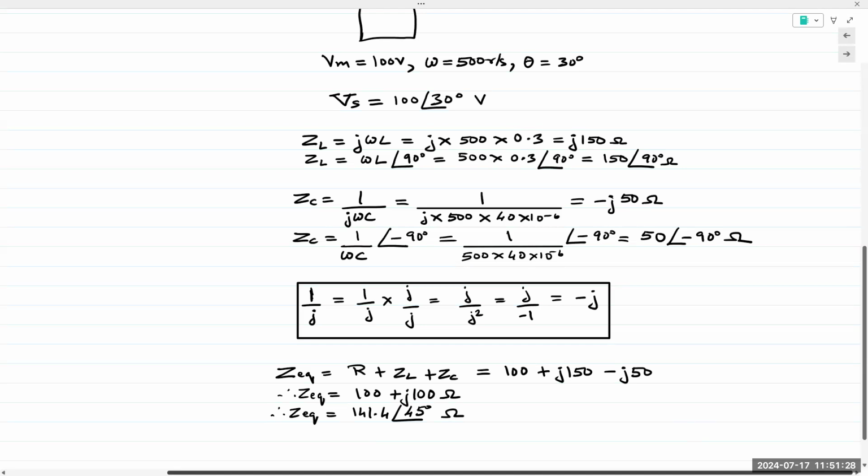So far, so good. Any questions? Now, if this was a series circuit and I asked you to find the voltage, what other technique comes to mind? Series circuit, applying a voltage, what happens to voltage? Voltage gets divided across all the resistors. The same thing happens here. You apply a voltage to a series connection of impedances, and a fraction of that voltage appears across each impedance. So if we didn't need to find the current, we could apply voltage division and find the answers directly.